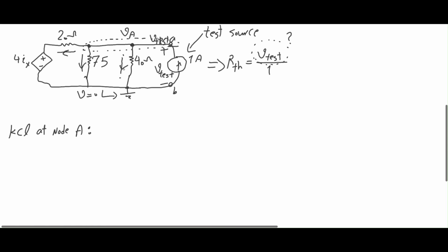let's try to find the KCL at node A. For all currents, we consider the voltage of the starting point minus the voltage of the ending point divided by the resistor. For this current, I'm going to call it I1, this one I2, and this one I3, and this one is just 1 amp that flows into this node and then peels off into I3, I2, and I1.